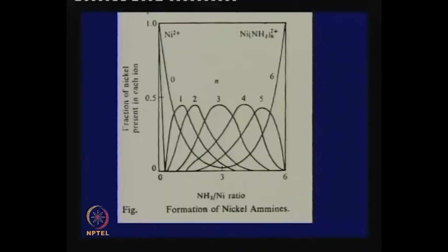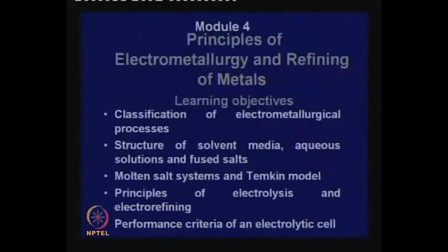Then an interesting thing I have also said is that while nickel and cobalt can be precipitated from acid solutions with hydrogen gas pressure in the normal range, by adjusting the pH, the particles that come out can be of various shapes depending on some catalysts that we put in the system, and we have talked about some catalysts that give rise to particular shapes of nickel nuclei. For more details, you have to see the book.